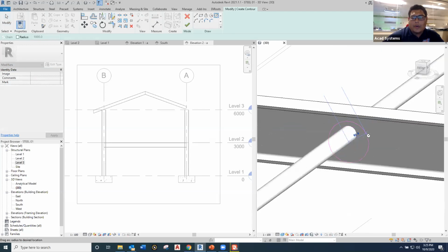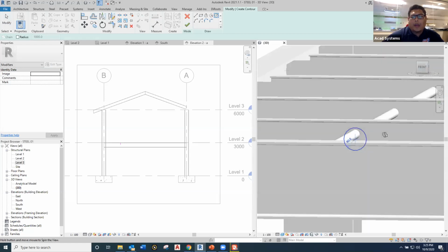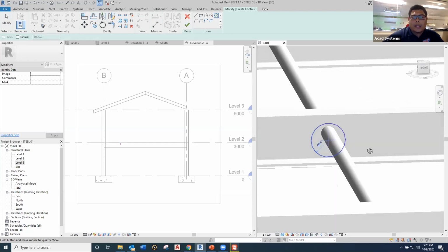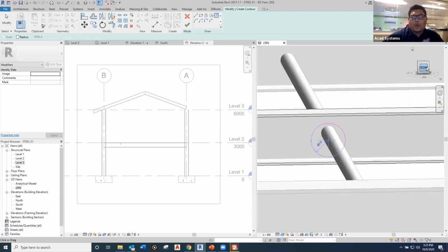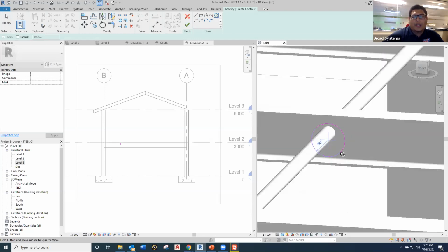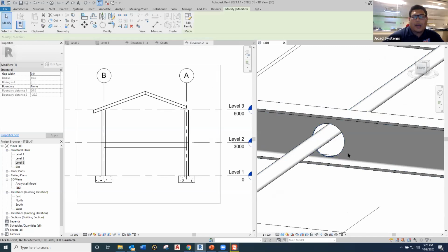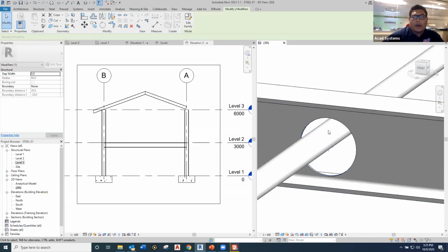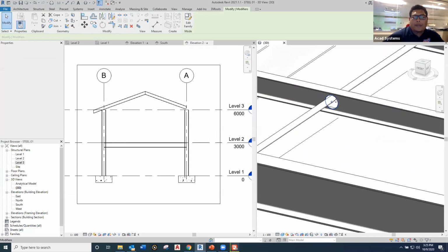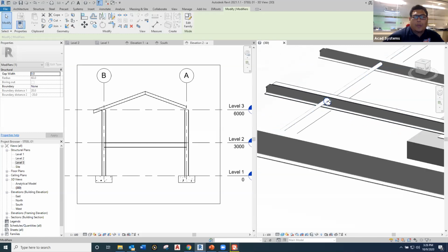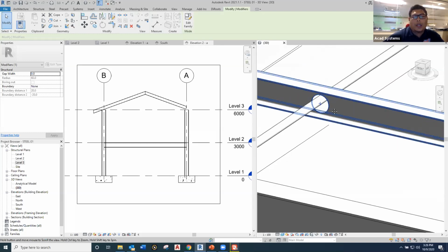Okay, then there you go, your surface. So this is the modeling in 3D, so that's why it has less accuracy. So what you need to do is go to front 2D view or any kind of section view to work with. I'm doing this to make it clear how it works, and then click finish, and it will automatically create voids. So for whatever structure it has here, it will allow the items to be voided, and then the clash will be solved. This is how we're going to use the contour tool.